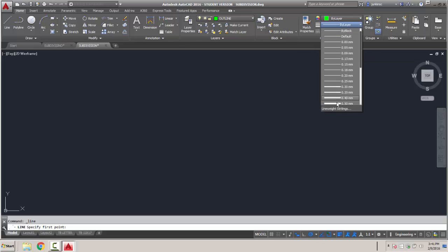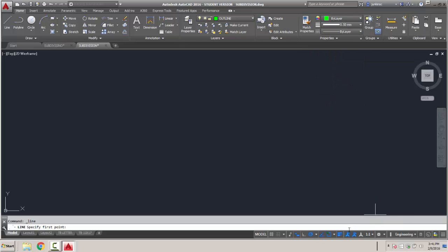I probably want that to be a fairly thick line weight. So we'll just start anywhere, and we'll go vertical. Make sure that your snap reference lines are on. My object snapping is on. Everything else is there. Our dynamic input is also on.